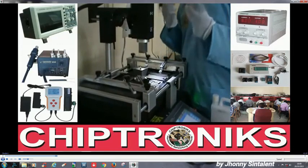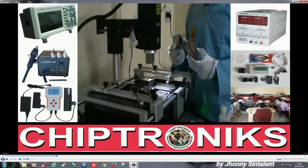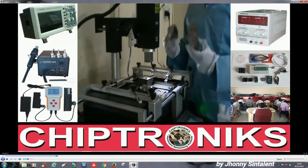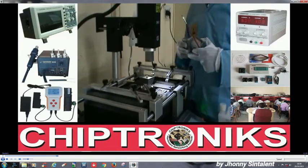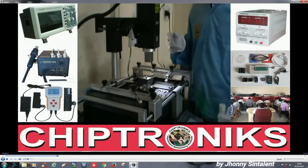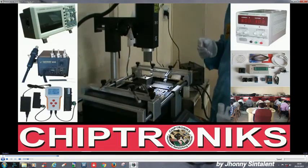If you have some specific designs, like if you want to remove a RAM slot or some other kind of BGA chip, then that can be custom designed. These nozzles can be custom designed for that process. But mostly for notebook motherboards, these three kinds of nozzles for the top heater are okay.